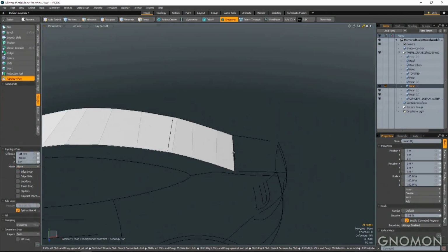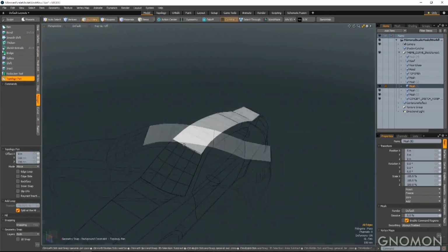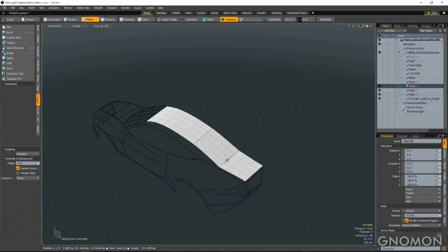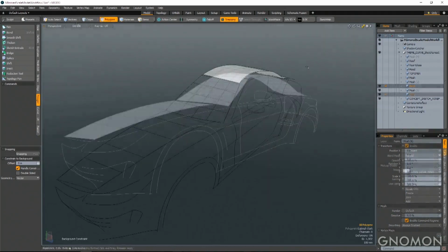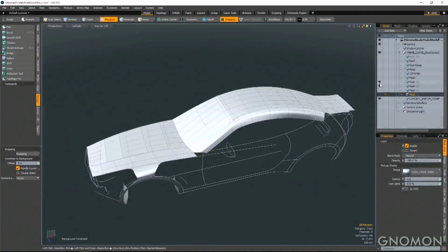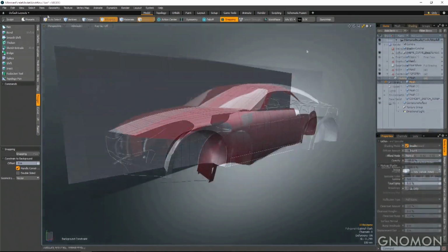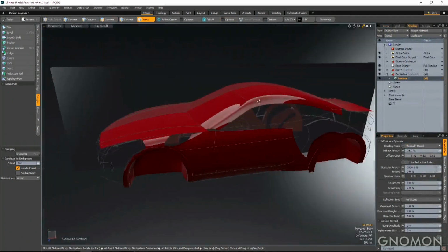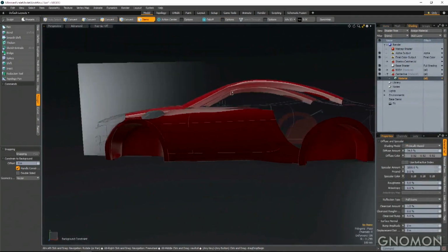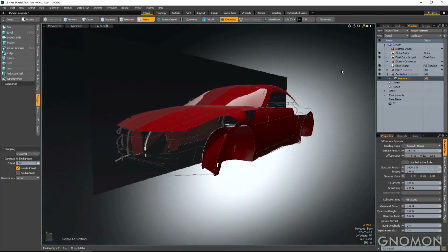It was just 2D lines, but a designer doesn't have time to sit there and noodle and craft every fillet and radius. So the ability to use the retopology tool and drape canvases over these wireframes is a big time saver. And then using the advanced viewport capabilities now in the Modo 10 series, you can put a mirror up to one half of it and start doing paintovers.